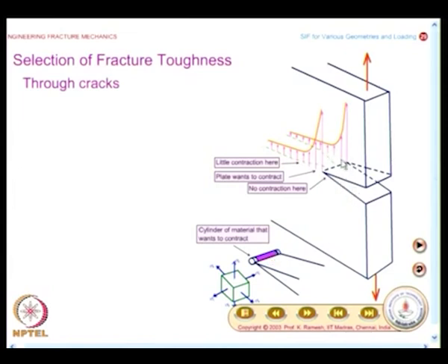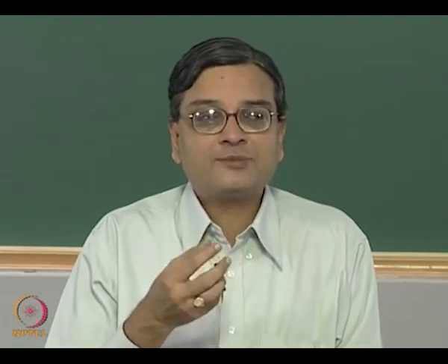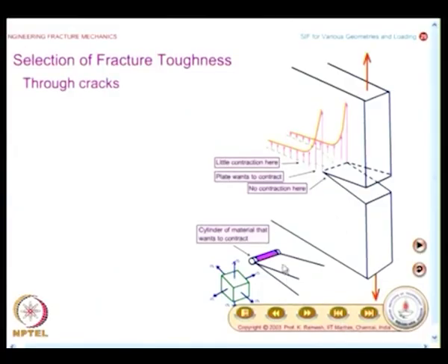And because of very high localized stresses, you will have essentially plastic deformation at the crack tip. So, when you have plastic deformation at the crack tip, it is prudent to take the Poisson ratio as 0.5. So, in essence, in thick plates you have triaxial state of stress near the crack, and that zone is indicated here. So, in the case of crack problems near the vicinity of the stress concentration, you could have under suitable circumstances a triaxial state of stress.